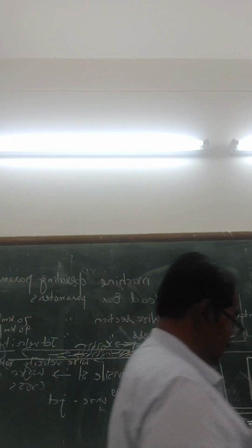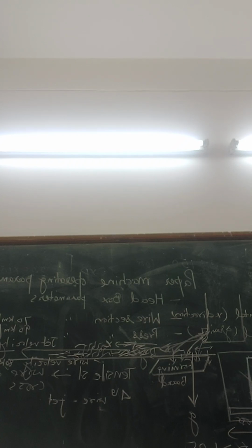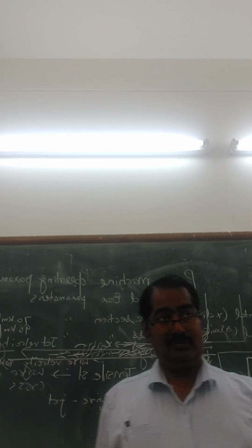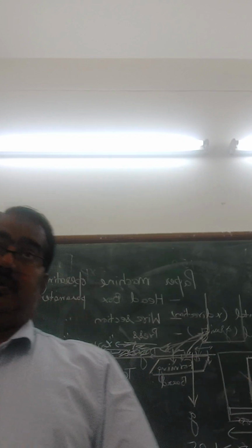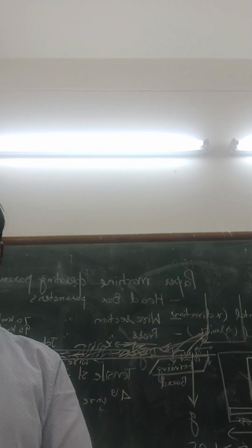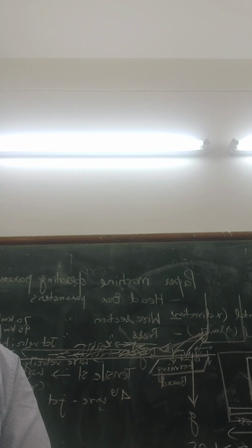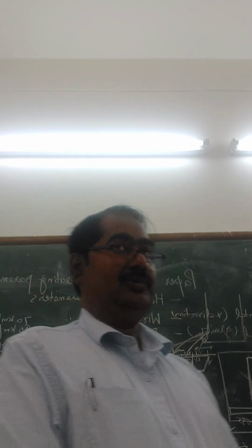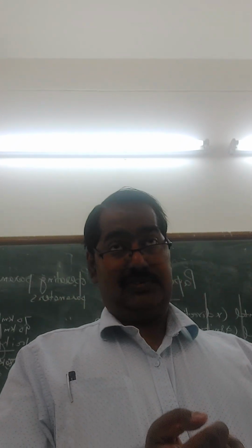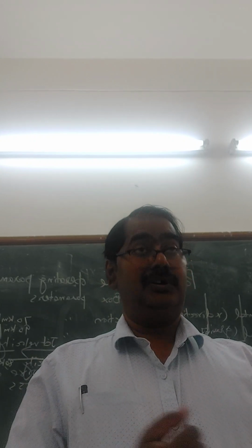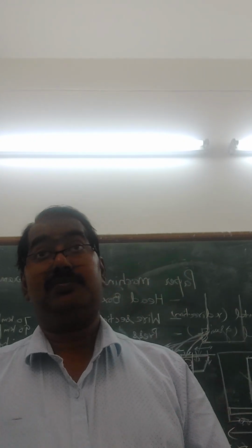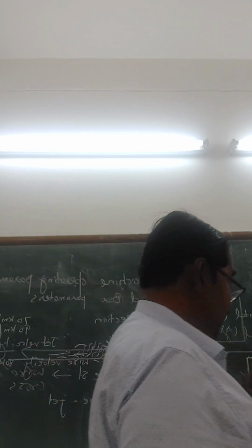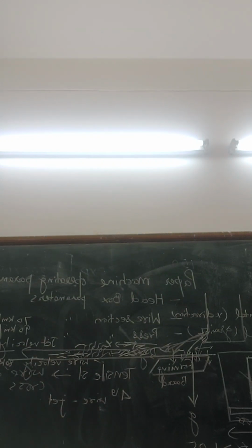Sometimes you get a cloudy formation, like on one side some more fibers are here. This is called the cloudy formation, and that is considered bad. That means if the paper has more cloudy formation, it will be rejected. Is it clear? So first of all, it will impact the strength properties, then it will impact the formation of the paper. And based on the formation of paper, again the optical quality will be affected.